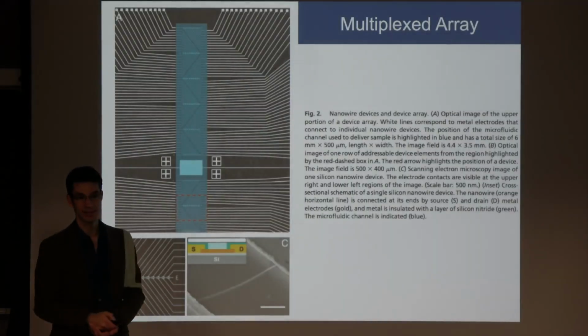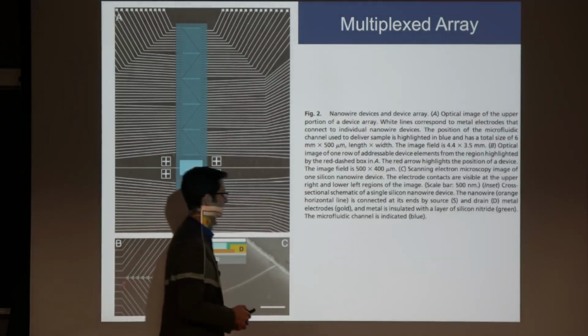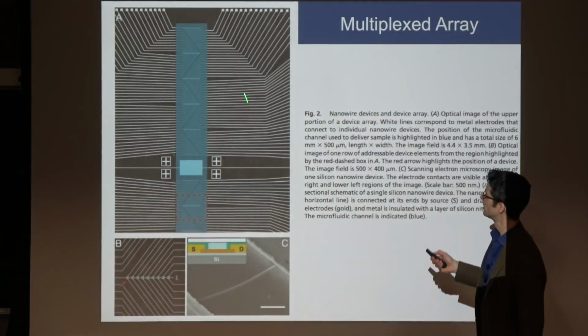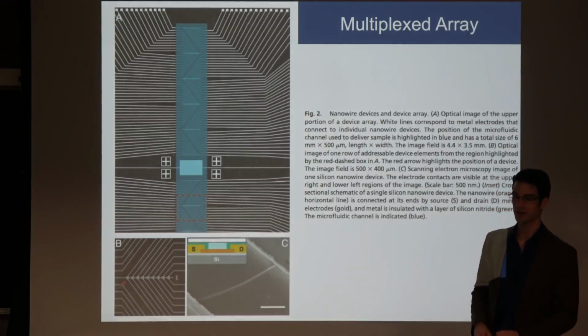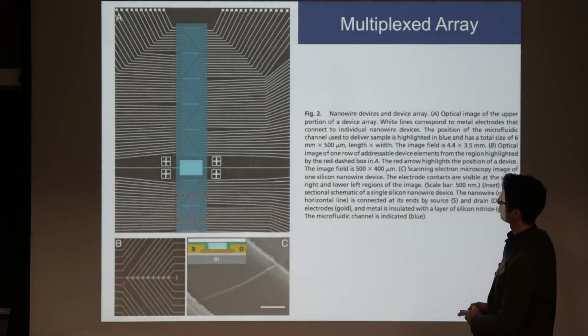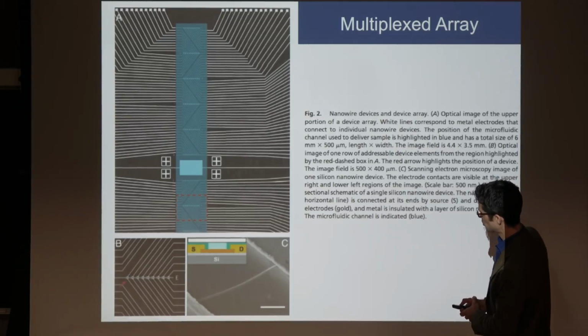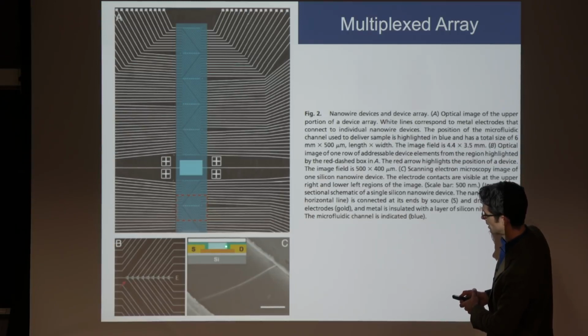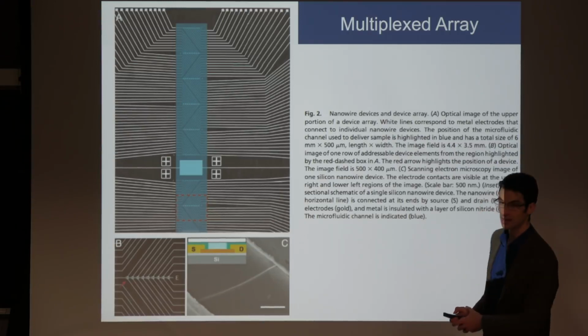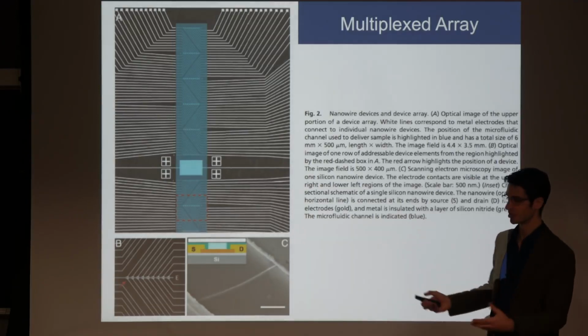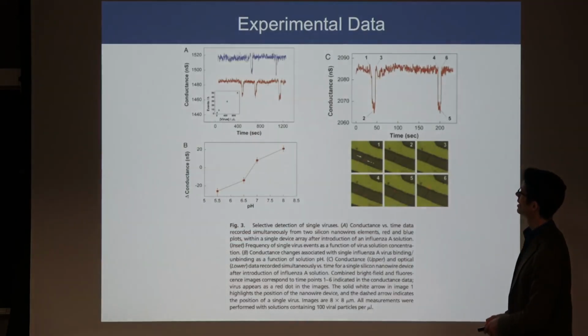Well, first, they did some electrophoretic alignment. First of all, they took these structures that were lithographed by electron beam lithography, so everything comes together. In each particular junction, I guess right here, we have nanowires that are crossing between the source on one side and the drain on the other. Source here, drain here, nanowire here that was aligned electrophoretically using these fabricated contacts. And what do we get?